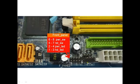And here comes the front panel connector. On the front panel connector we connect the power switch, the reset switch, power LED and hard disk LED. The front panel connector has a total of 10 pins, but the 10th pin is the no connection or dummy pin. The pin that is diagonally opposite to the 10th pin is 1. The pin counting is like this: 1, 2, 3, 4, 5, 6, 7, 8, 9, 10.